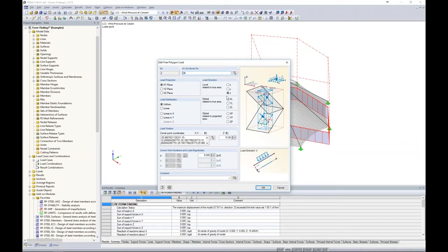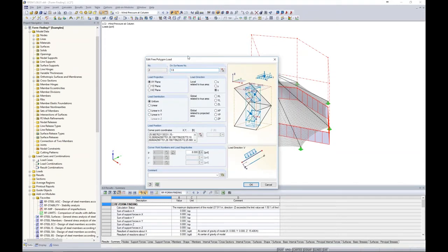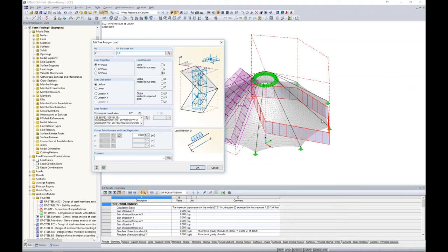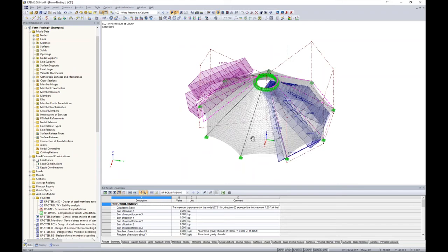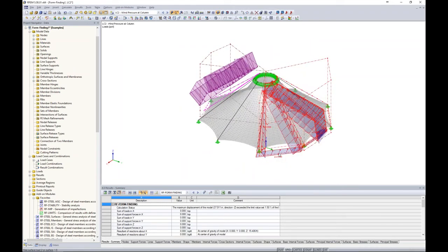Looks like I applied this to surfaces all. It's the same thing. You can leave it as all or type in surfaces 1 through 9, but you can see the display is a little bit different. It just goes back to it being projected. We can project down through multi-level story buildings as well. But just for display purposes, I'm going to select this as all just so that it's very clear this is a suction pressure at the rear of our structure.